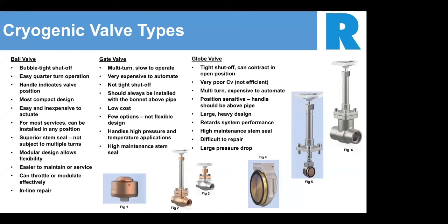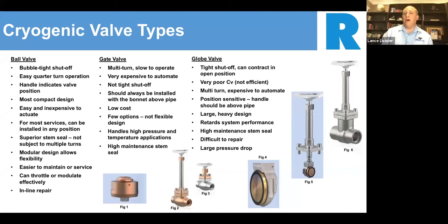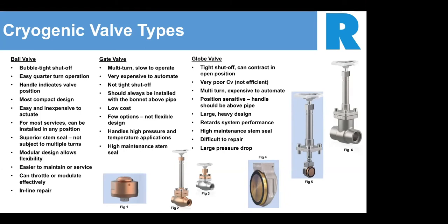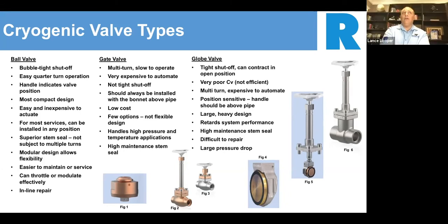Most of the leaks in our ball valves occur because the valves are installed backwards. I can't tell you how many calls I get a day saying my cryogenic ball valve is leaking, and most of the time it's just the direction in which you put it in. There are particular ways to install it, and we'll go into that a little later on.